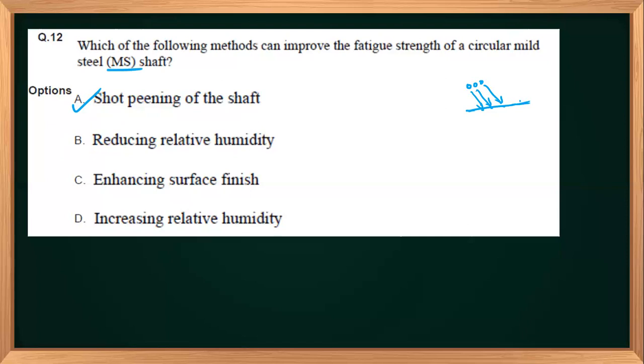So that's why in many of the places where you use MS steel, it will have anti-humidity paints or non-moisture absorbing kind of coatings, right? So if we can use MS plates or an MS shaft in a non-humid environment, that will be better, right? So that it can reduce the reaction with atmospheric oxygen, and reduce the contamination, so that it will improve your fatigue life. So this is also one of the things.